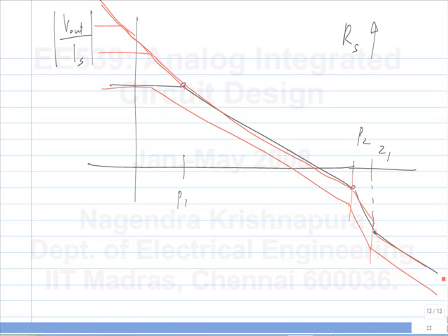And that again we'll see is one of the types of op amps we'll use in feedback systems. Because this Bode plot does look like something that we would want to use in feedback systems, right? It has a nice 20 dB per decade slope all the way from very low frequencies to a point after which it crosses. Here I shouldn't say unity, because this is a dimensioned quantity and the unity of this doesn't make any sense. It doesn't have any significance. But it does have a 20 dB per decade slope for a large range of frequencies.